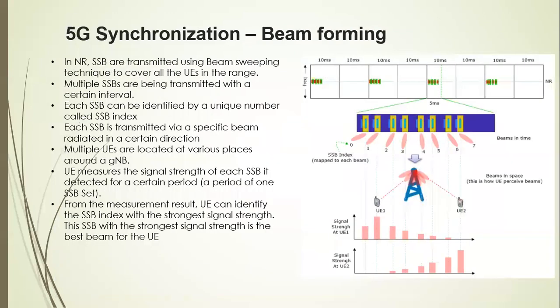Because the system information is common information and many devices have to receive it, it is the device's responsibility to find its own most preferable beam, sync up there, and read the PBCH information and proceed further. But once the synchronization is done and we have completed the RACH procedure, when the UE has a dedicated RRC connection, then beam sweeping may not be required for the UE.